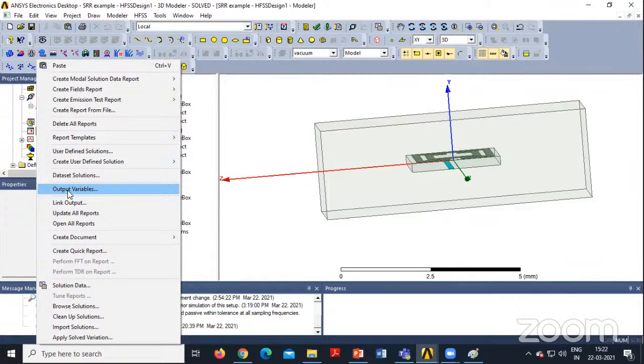I need to draw the dispersion diagram if it is the transmission line approach, or I need to draw the refractive index diagram, or epsilon r diagram and mu r diagram: mu r versus frequency, epsilon r versus frequency, or refractive index versus frequency. All these three graphs should be drawn if you are treating the SRR with the resonant approach.